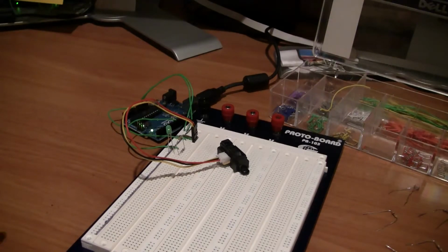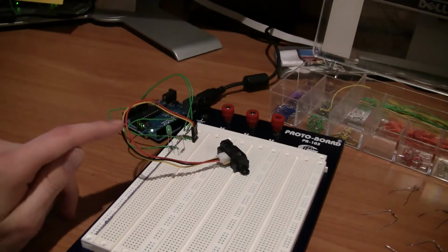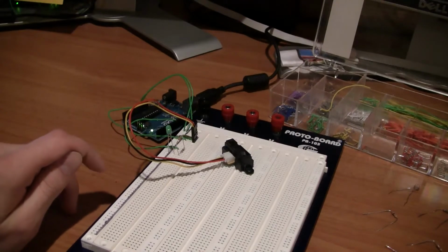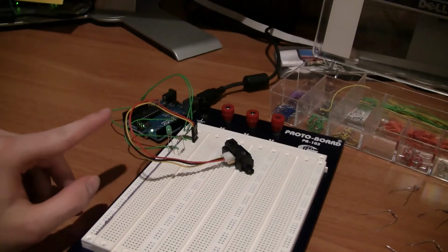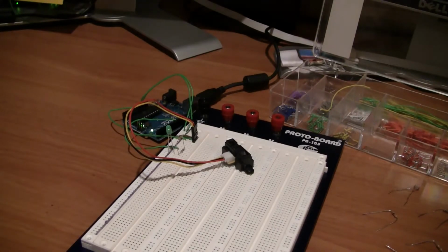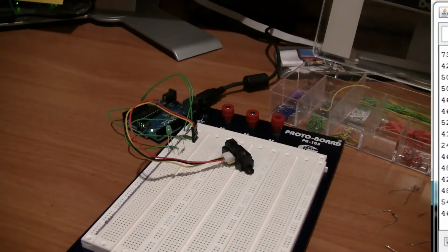All sensors that come like this will usually have 3 wires, a voltage wire, a ground wire, and a sense wire. The red wire, we give it 5 volts. Ground gets connected to ground, of course. And then the yellow wire returns a value between 0 and 5 volts that we can feed into the analog digital converter in the Arduino and use it to measure a distance value. You'll often notice that these kinds of sensors will give you a broader range because they've already designed it to operate on the whole 0 to 5 volt range. You can also buy these sensors in 3.3 volt iterations and other voltage versions.